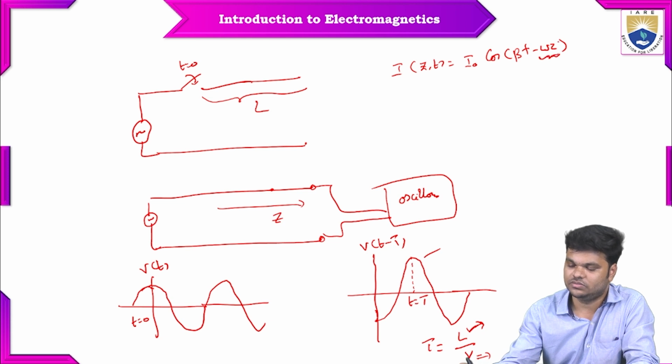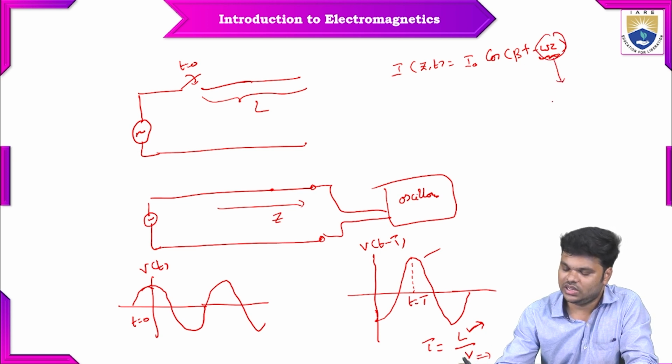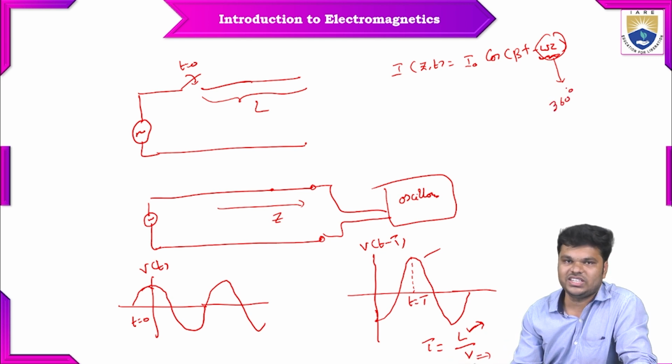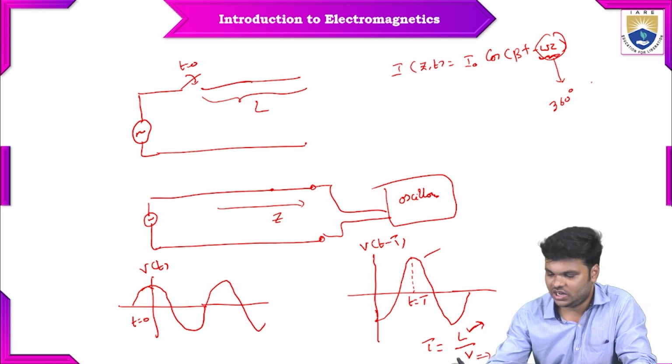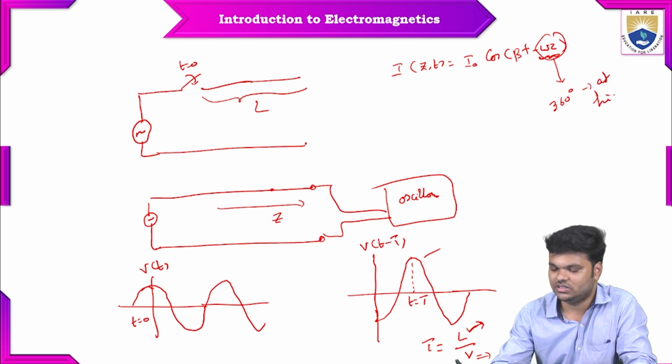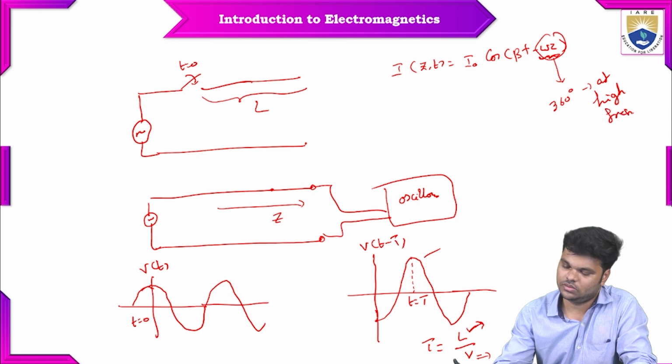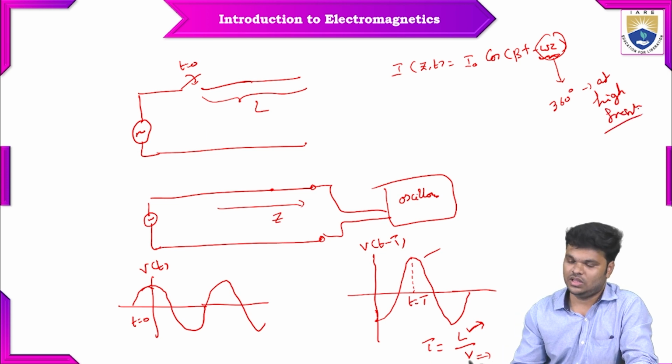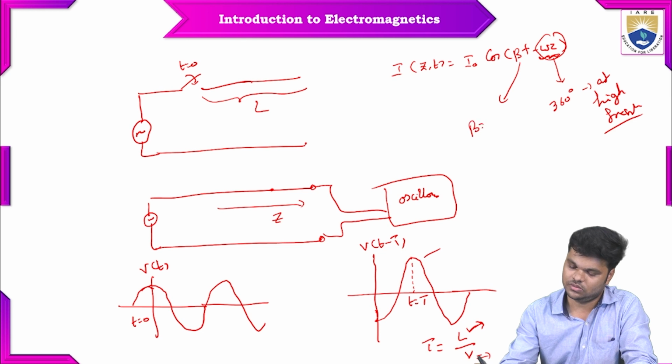or phase shift, and this one varies from point to point. And this phase shift is a significant fraction of 360 degrees. It's a significant fraction of 360 degrees, especially at high frequencies. And this beta is called the phase constant.